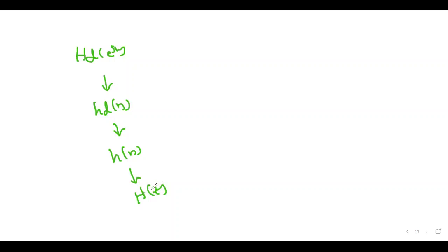After calculating h of z, it is not physically realizable because of the non-causal system. Therefore, we need to multiply by the delay at the center of symmetry. Then we get h dash of z. This is the physically realizable FIR filter. That's it. This is the flow of doing the problem.